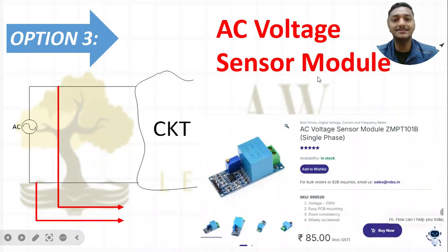So there is an AC voltage sensor module. This is, I would say, low cost, 85 rupees. So what actually is this particular module? It is a ZMPT101B type of module. What this module will do, you can see that these two pins are there. You can directly connect the two terminals across the AC to this particular thing, not plus and minus, my phase and neutral connect here, and there are 5 pins available here.